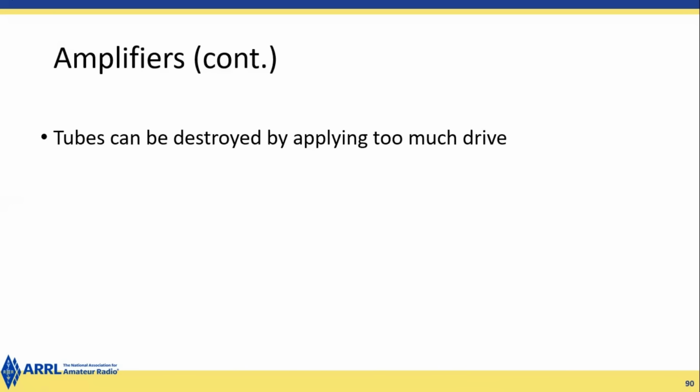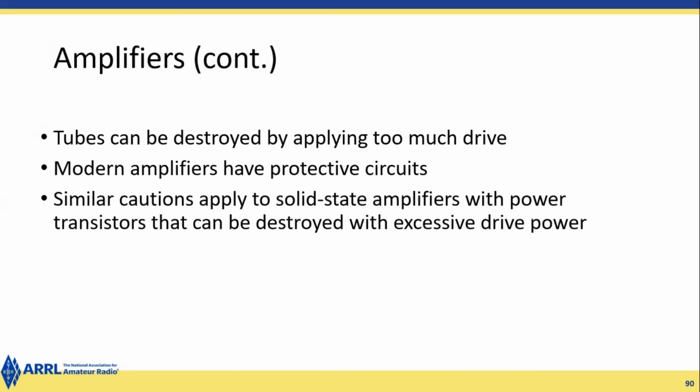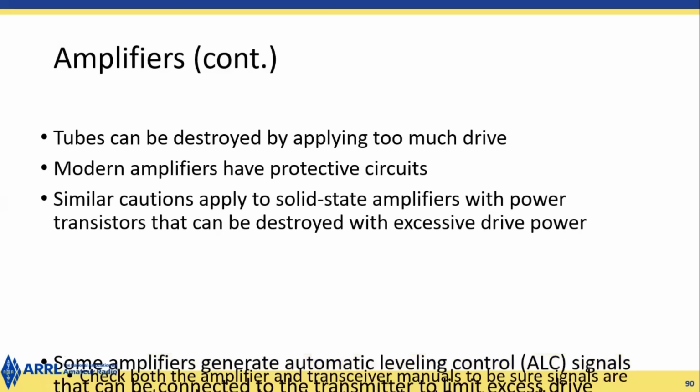Tubes can be destroyed by applying too much drive. Modern amplifiers have protective circuits. Similar cautions apply to solid-state amplifiers with power transistors that can be destroyed with excessive drive power. You've got to be careful. The controls are pretty good these days, protecting them.